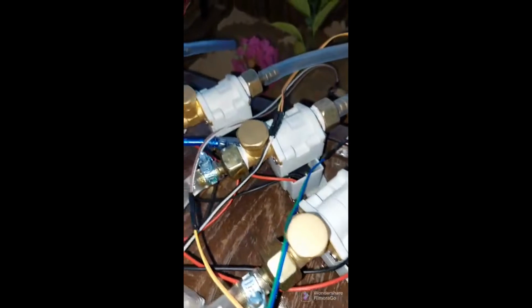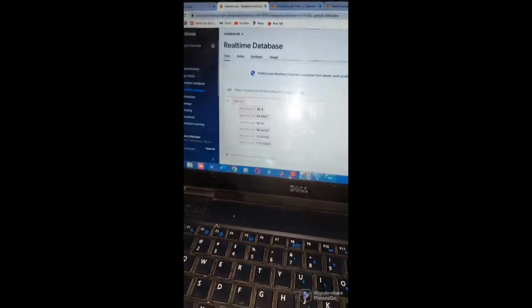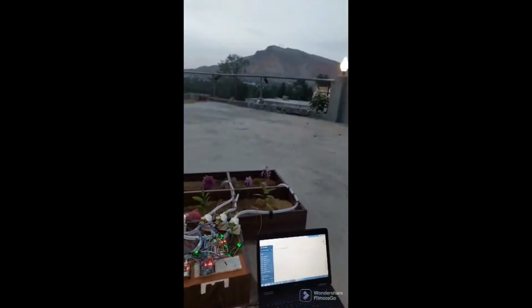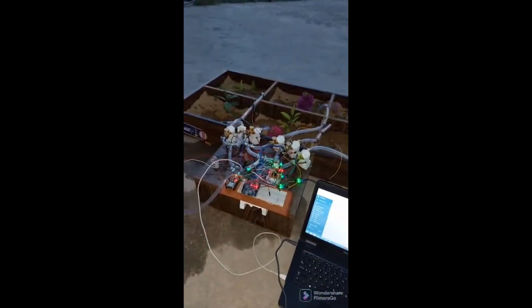In the code of our smart irrigation system, first is the project ID, then the project token from the database, then our Wi-Fi name and secret Wi-Fi password. After that we have initialized the values of Arduino and ESP32 for the moisture sensors. We connect Arduino with ESP32 through TX and RX pins, which is serial communication.